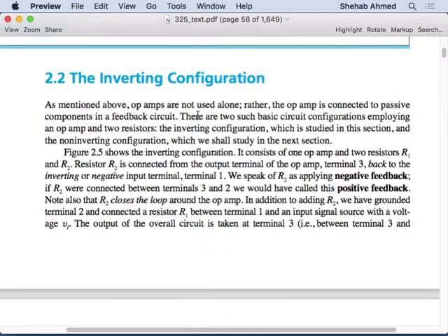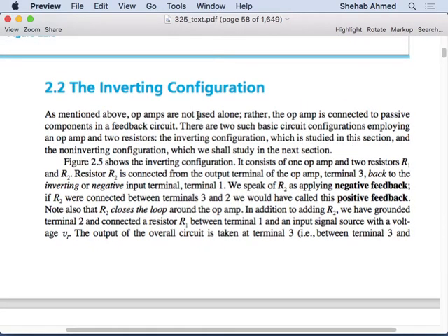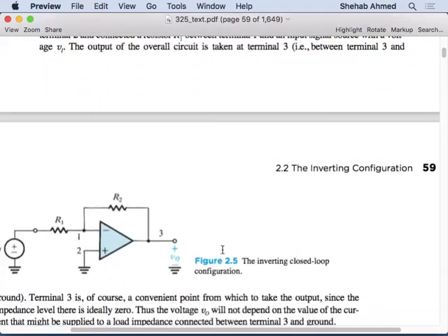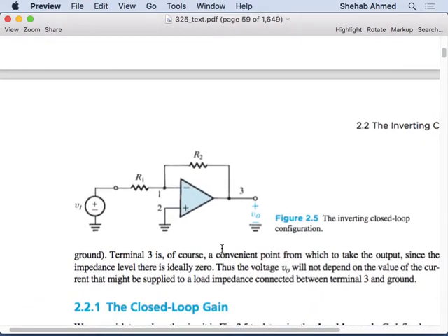So now, everything we've been talking about was, we said that this op-amp is a nice device, right? It's a really nice and interesting device. But what was the main problem so far? I can only use it as a comparator. That is the big problem. It is useless, and it will saturate. If I use it as a comparator, if one of the terminals is larger than the other, it will either saturate to the positive rail, positive VCC, or the minus VEE supply, or something less than that. So it's not very useful when I have a device that can be used only in that fashion, right?